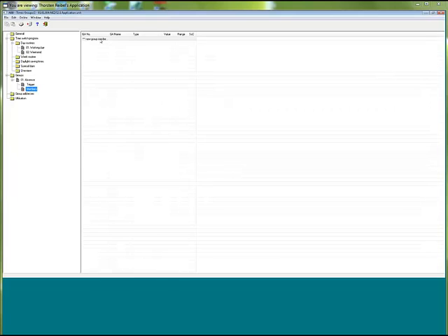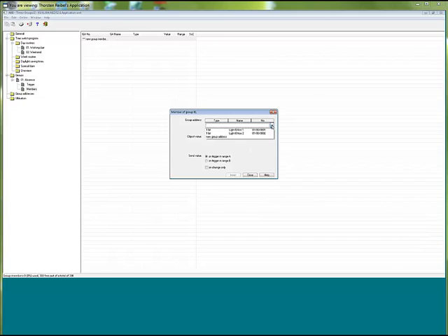I have to create group addresses as group members, of course. So again, I can choose the existing one. You see light again. If I insert a group address, you can decide what shall happen with this telegram. Shall it be sent as an on or off? In this case, on. And you can decide at which trigger function or which trigger value it shall be activated. Range A is off, range B is on. It's defined here for a 1-bit trigger. So I say if the trigger is sent with value on, then I switch on this light.